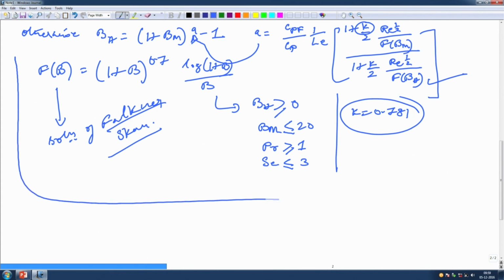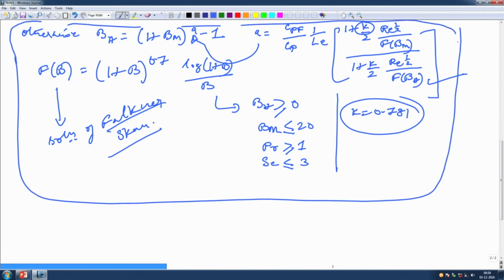So, using the gas phase results and the model of a spherically symmetric droplet evaporation, because that was our starting point, after that we included the convection effect within the liquid. So, for this convection effect, using the gas phase part of the analysis, this is what Sirignano and others showed to be valid. Got it. Now, obviously we have done this, we know what the heat and mass transfer is, but there is a certain catch now.